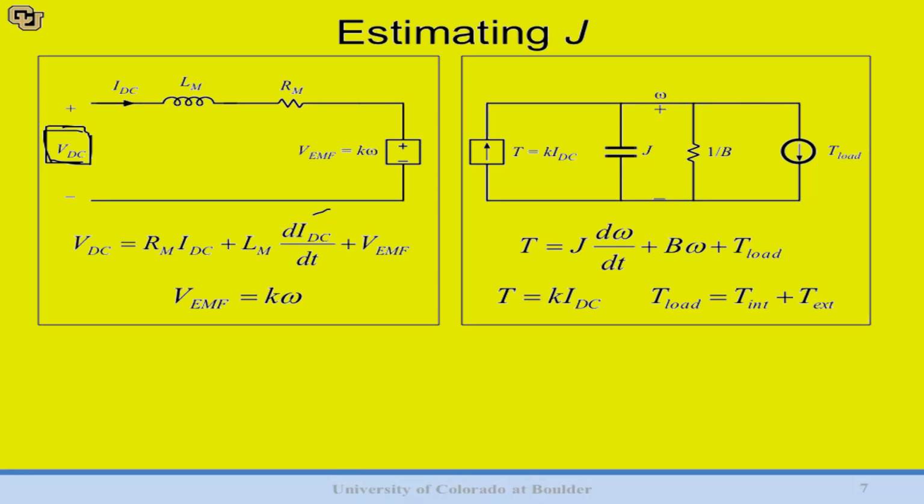What does that mean? Well, if we have time down here and VDC up here, and if we just go along, here's our voltage, and then at some time we just turn it off. What we should see is our voltage starts to slowly sort of drain away and ramp down as soon as we turn it off. When you turn off these supplies, they simply open circuit their output, and so we end up with an open over here.